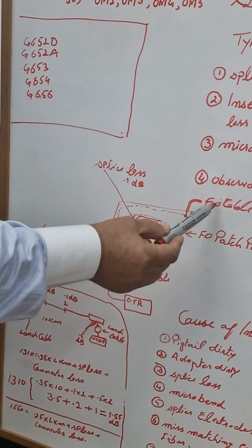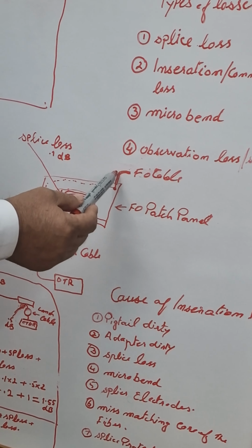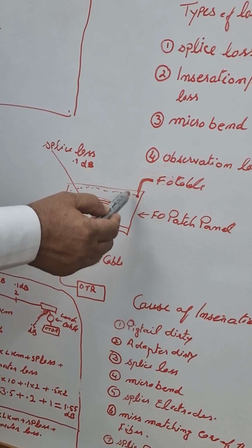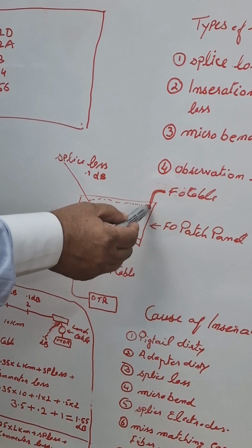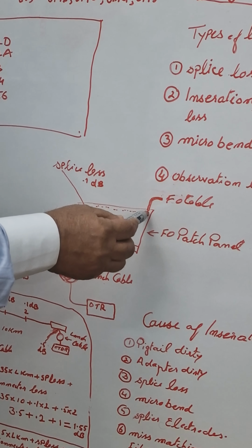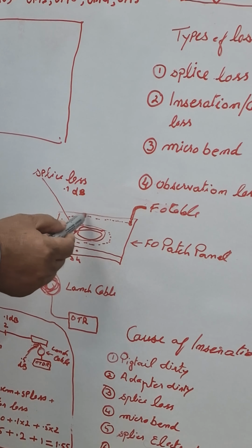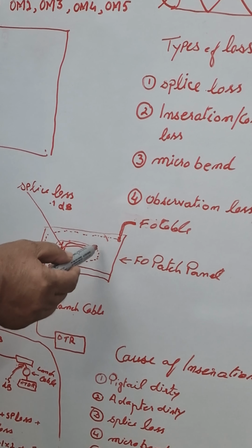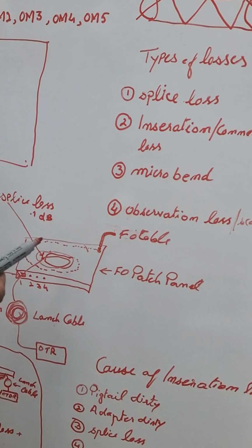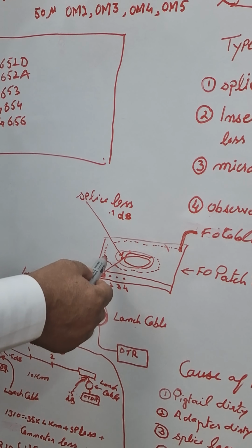Now this is, for example, one patch panel. So on the fiber optic patch panel, this cable comes inside the panel. It should be tied here with the strength member, tied at this point, and then the tube should be left one circle inside, because for maintenance purposes later, if you require fiber or something happens, you can use this tube.